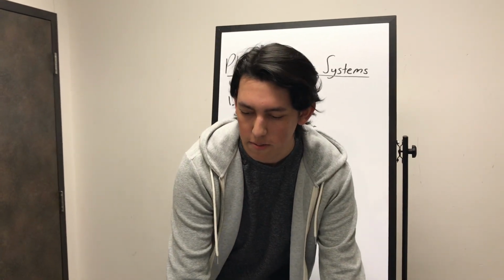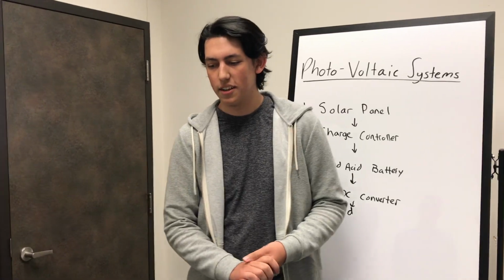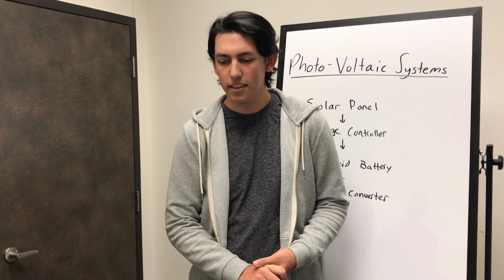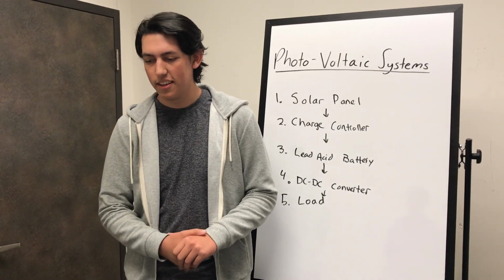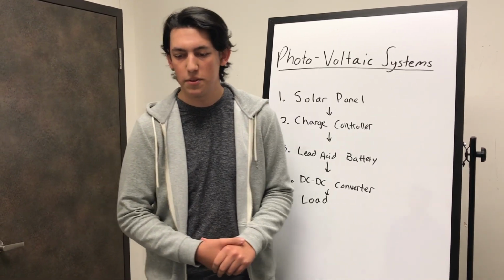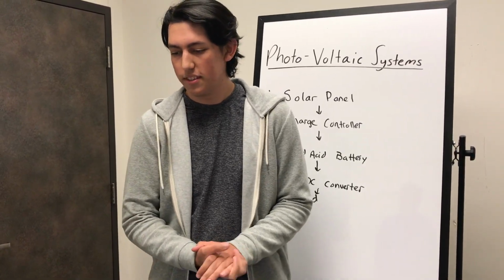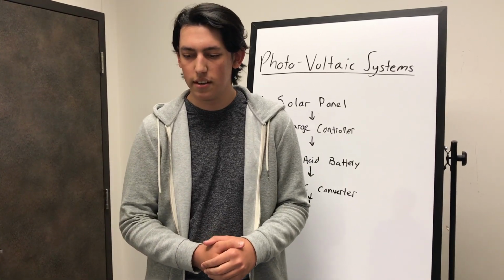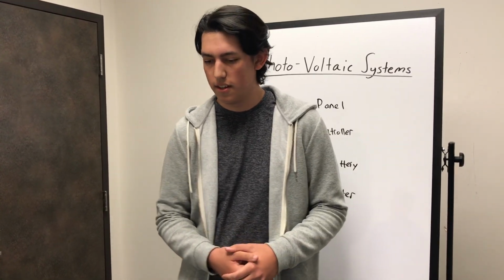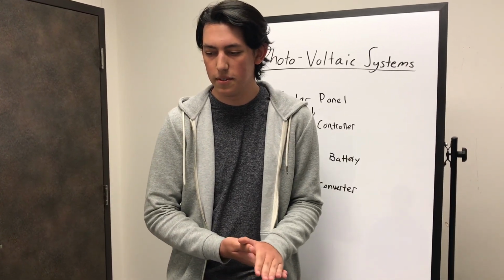As you already may know, silicon is a non-metal with conductive properties, which allows it to absorb and convert sunlight into electricity. When light interacts with the silicon cell, it causes electrons to be set into motion, which initiates the flow of electric current. This is known as the photovoltaic effect, and it describes the general functionality of all solar panel technology. The photovoltaic process can be simplified into three main steps.